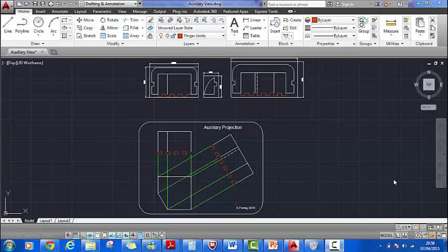In this video we're going to take a look at creating different line thicknesses. We need to create different line thicknesses in order to determine between a vector or a raster cut on the laser cutter. Again, our vector cut is a solid cut and our raster cut is an engraving.